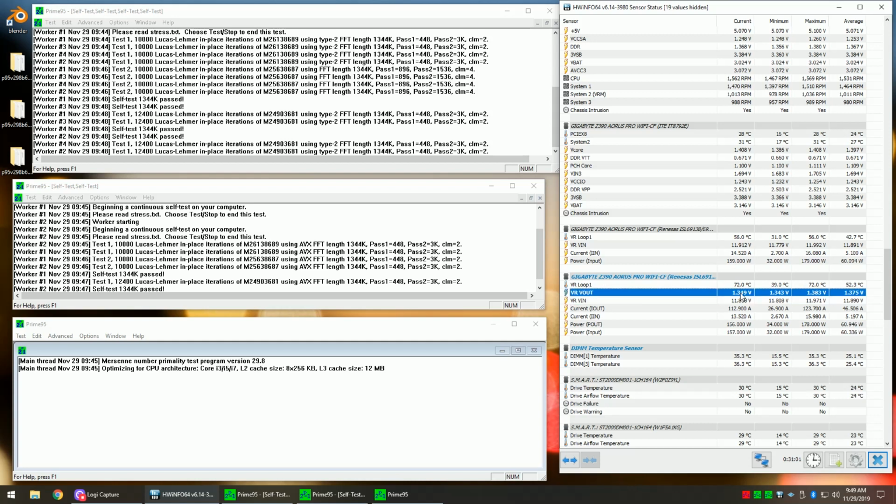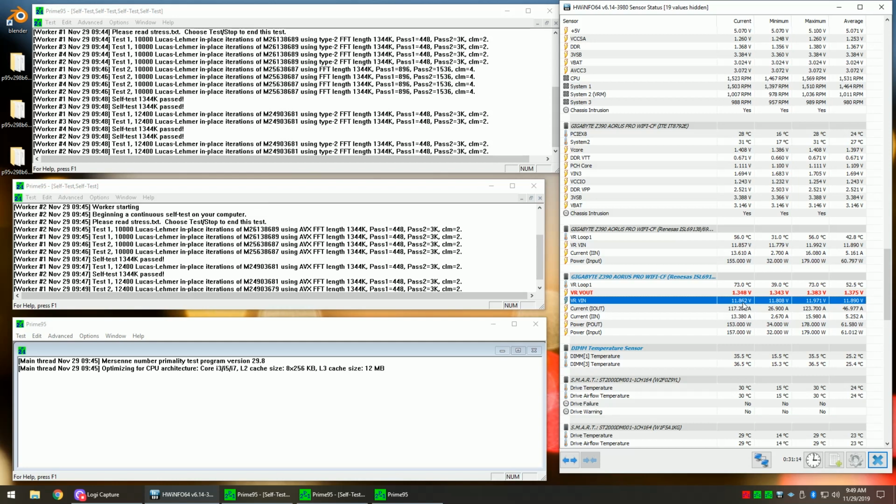So it's going to be lower now that there's load on it. Not a huge concern, as we know that this is going to be lower and it was already good while sitting idle. But I do like to check this to make sure there isn't any crazy LLC or load line calibration settings that are causing the voltage to spike for some reason. Spikes above 1.4 would be something that I would consider unsafe, and I'd want to immediately shut down, go find out what caused that, and get that fixed before continuing.